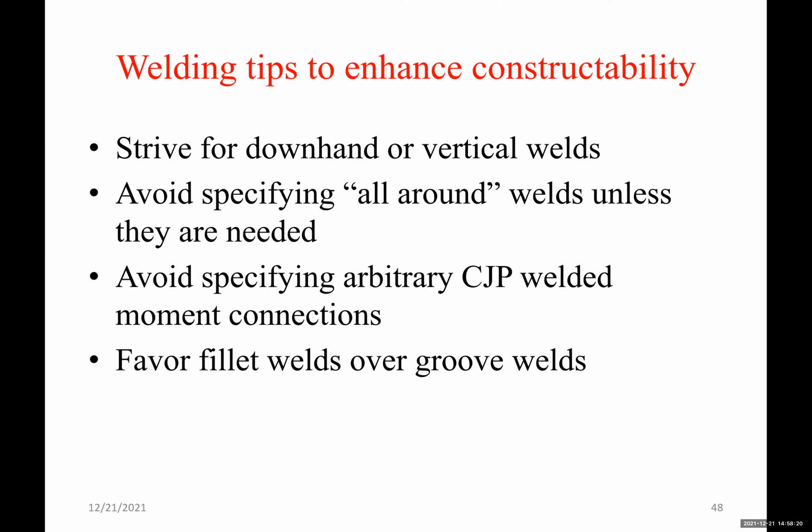Avoid specifying arbitrary CJP weld moment connections. As we said at the beginning, design the moment connections, provide the forces, provide the moments at the moment connection. For these forces, you can design with smaller plates, with fillet welds, maybe with fewer bolts or smaller size bolts, and avoid using CJP.